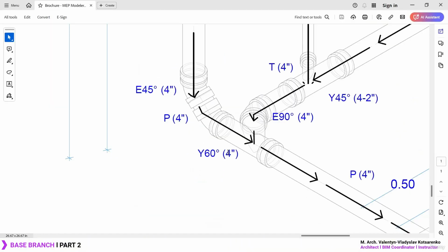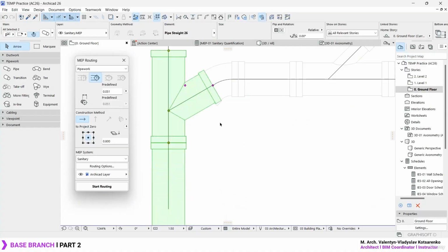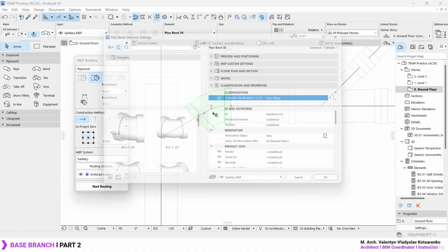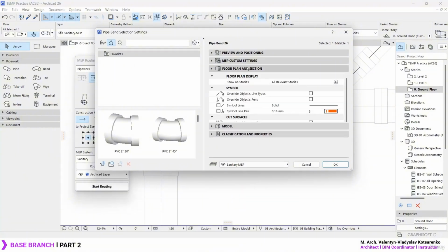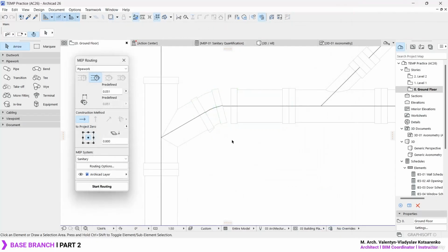Okay, so yeah, something's a little bit off because this one is actually 60 degrees, but we also got an elbow over here. So how about we first move maybe this element in branch, and then we might set up the elbow instead of maybe 45 degrees. Let's see if we can set this to 30 degrees. Press OK.